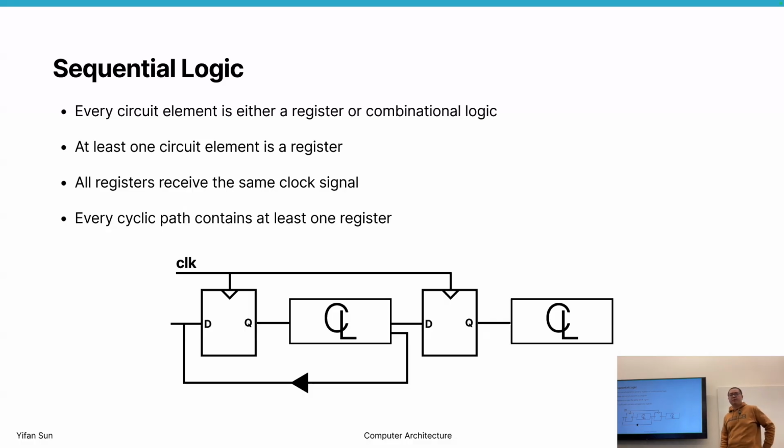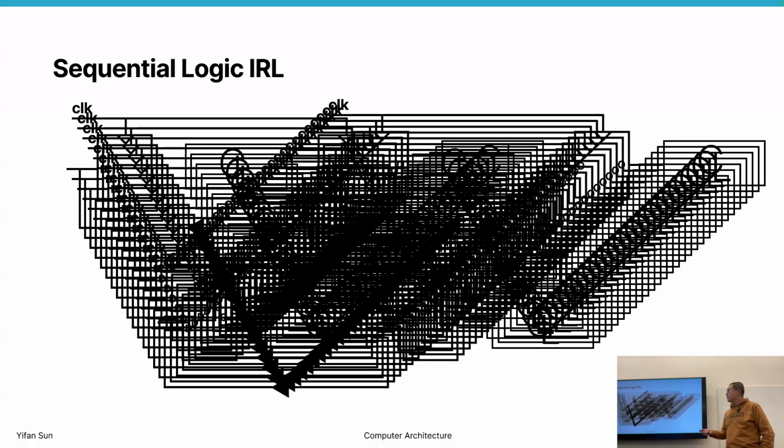If we use a state map, what we're basically designing is what is shown here: one group of registers, a few bits, and a combinational logic. Since we're saying with Karnaugh map, we can probably only do 4-variable, 4-pin, 4-wire optimization, our register can only have 4 values. That's the limitation of what we can do with hand derivation. But in reality, things are much more complex.